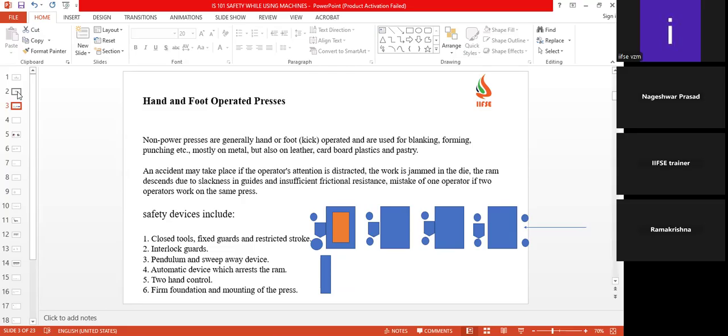Apart from that, there will be specific hazards based on the type of operation and how the people interact with the machines. Take this example, in sheet processing machines, I mean press machines. While the die was moving out of the bed, the person tried to take out the guard which is there for scrap removal, or to create a path for the scrap into the conveyor. He met with an accident.